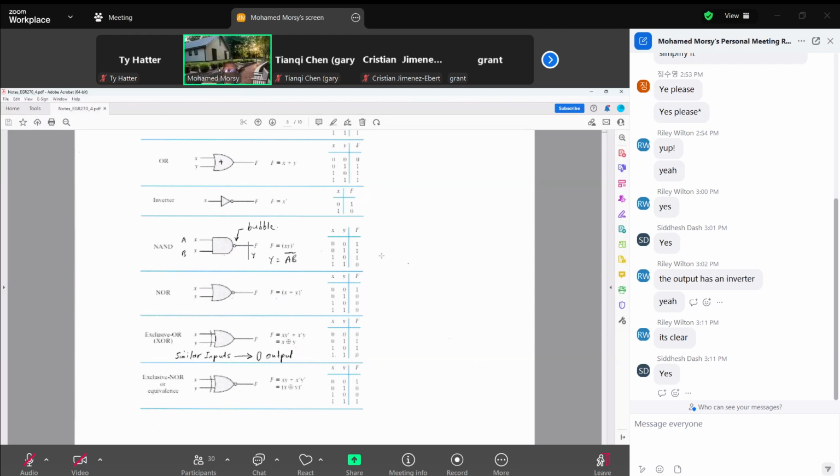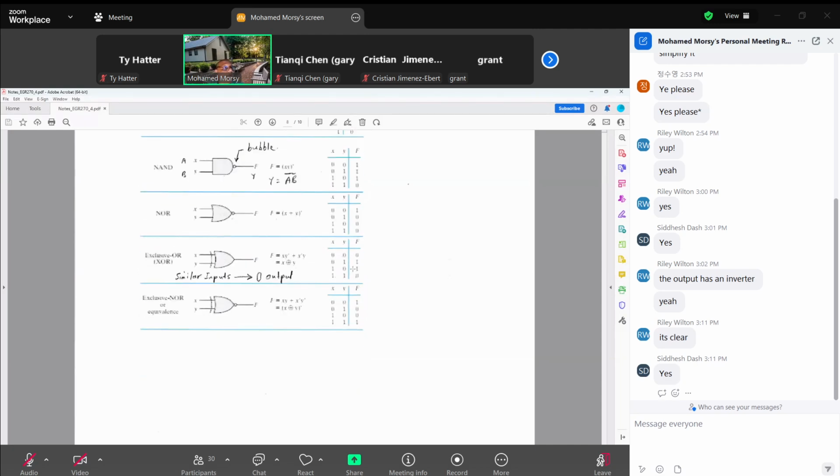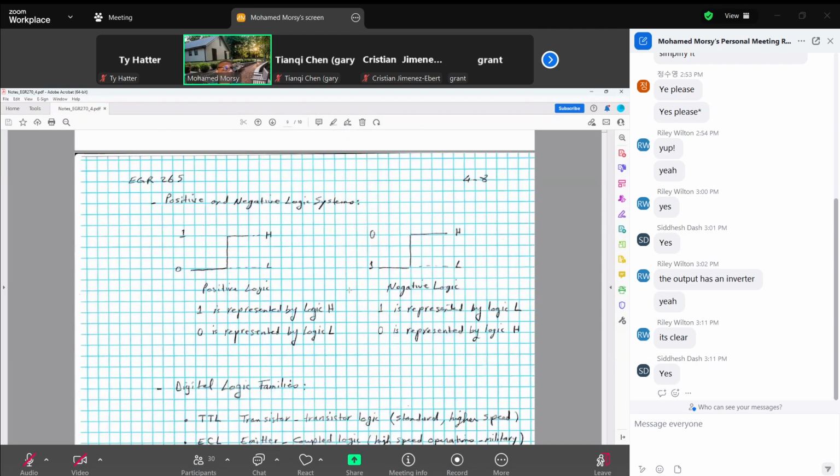So when you connect the input to logic high, you connect this switch to 5 volt. When you insert the input 0 to the gate, you connect this input to the ground, which is 0 volt, right? So of course voltage and current are related, but when we say logic high or logic low, we specifically talk about the voltage levels, as we mentioned.